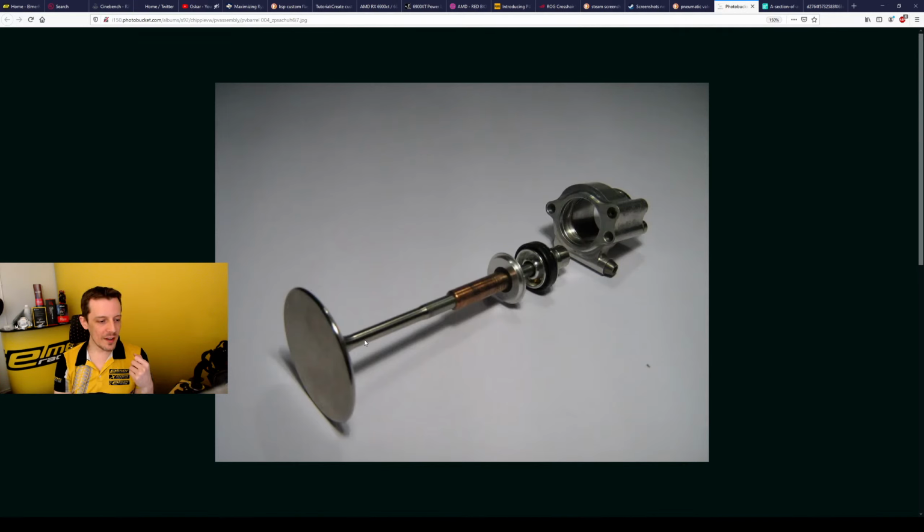Okay, so this is apparently an F1 valve. When you start getting to RPM limits, or acceleration limits more correctly, that start creating unsolvable problems with coil springs, then you need to move over to some better systems. You can optimize the ramp rates on the opening, and the closing ramp, of course. You also want to have it just barely contacting the cam lobe on the closing, until you get close to the seat, and you need to decelerate the valve again.